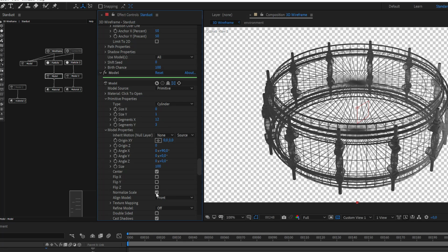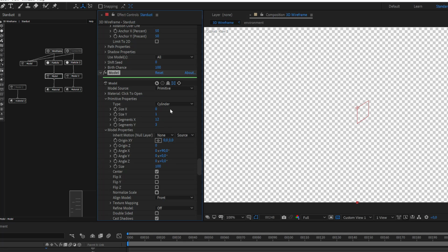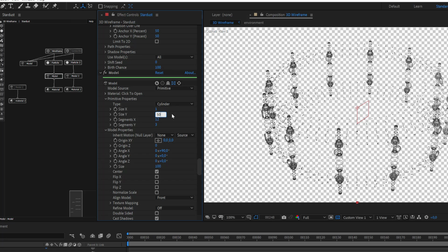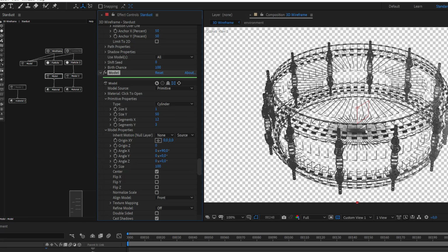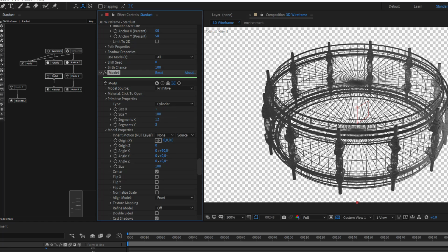It's exactly the same. If you do not use this, then you can put in your value 1 by hand here, and then you can choose whether you want it to be, for example, just 50% of these edges, or whether you want it to be 100% covering these edges. So these are the two options that you have to align your models properly along the edges.